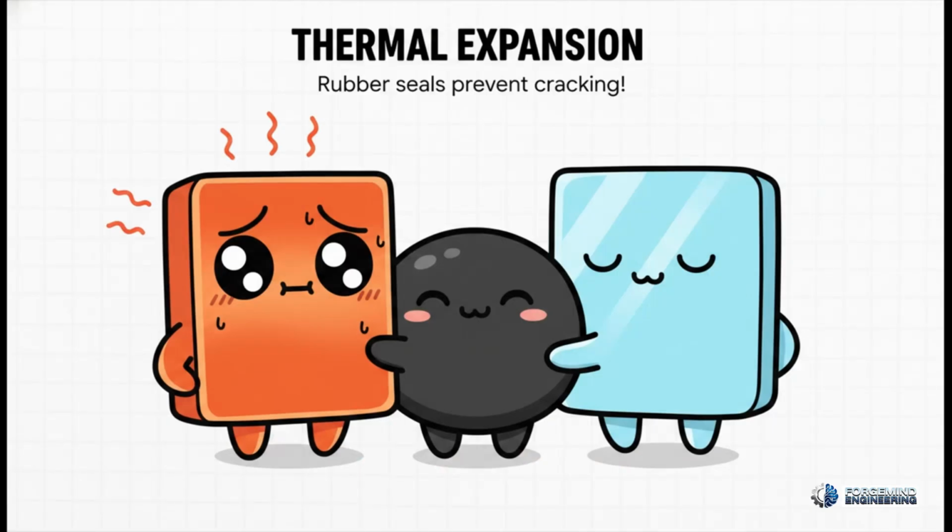We also have to strictly design for dimensional compatibility in the real world. Think about it. Utilizing flexible rubber seals between glass and metal frames is essential to absorb differing thermal expansion coefficients. If we skip those flexible components, everyday temperature variations will just induce massive stress cracking out in the field. It's a simple integration, but absolutely crucial.